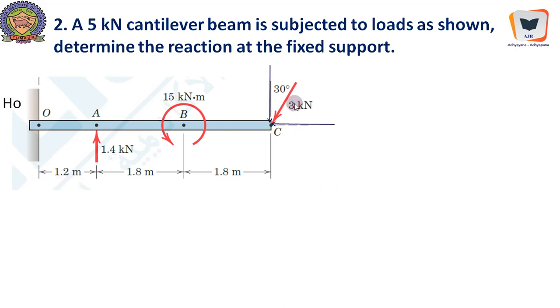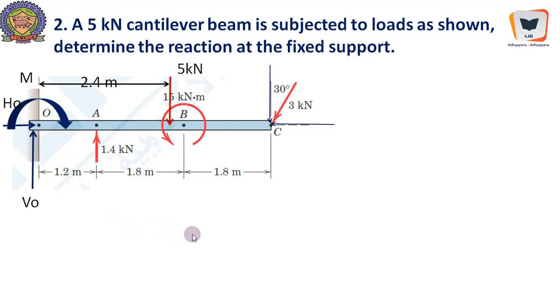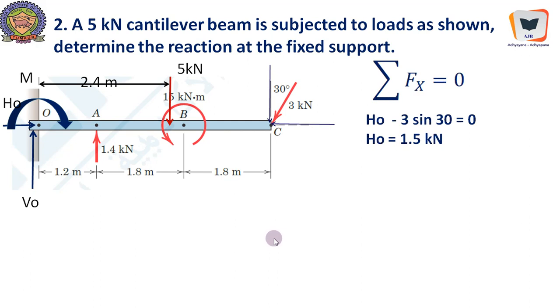At the fixed support, there are horizontal and vertical components. The fixed support will have a vertical reaction going up, and this is our assumption anyway, and a horizontal reaction going to the right. We will assume positive reactions here and a positive moment. We know from the third tutorial that a fixed support will have three unknowns, and degree of freedom equal to 0. Therefore we need to apply all three fundamental equations of statics.